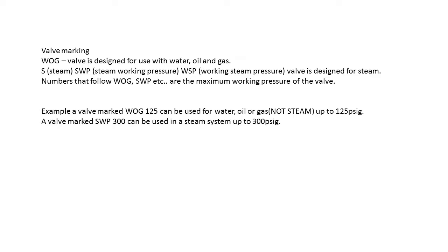After these markings, you will find a number, usually 125, 150, 300. That is the actual maximum working pressure of that valve. You cannot exceed that pressure, otherwise the valve could fail.